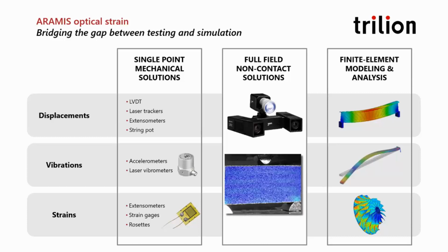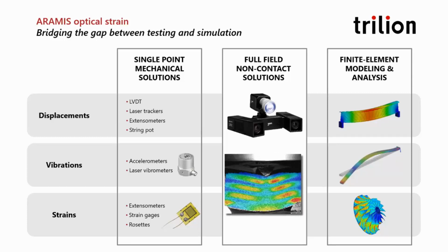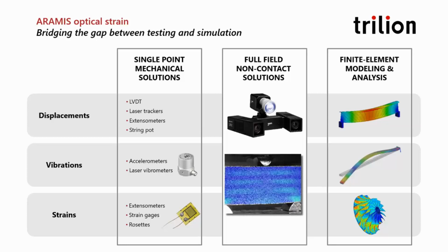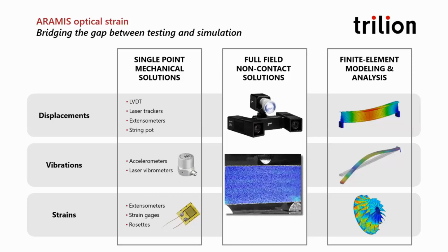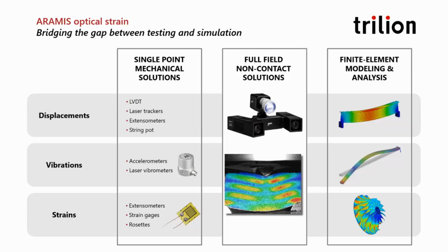It's very ergonomic, it's self-contained, it's not wires everywhere. And what's really interesting is after you collect the raw images, you can define points of interest at the end of the test. So you're retroactively inspecting the data and placing virtual strain gauges, virtual extensometers down.